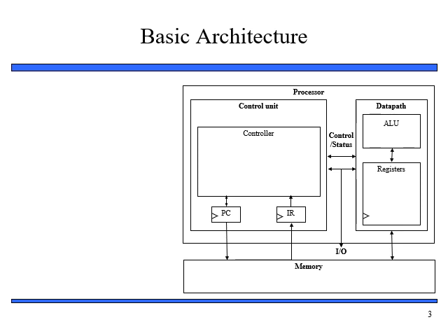The control unit comprises of controller that is connected to PC and instruction register, which is then connected to memory for getting the instruction from memory, and PC program counter is used to fetch next instruction and it increments itself when instruction register fetches instruction. Whereas data path consists of general purpose ALU registers, and the registers are connected to memory. Control and data path are connected through status and control signal as well as through input-output signals.